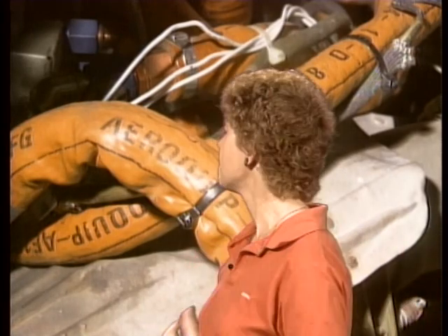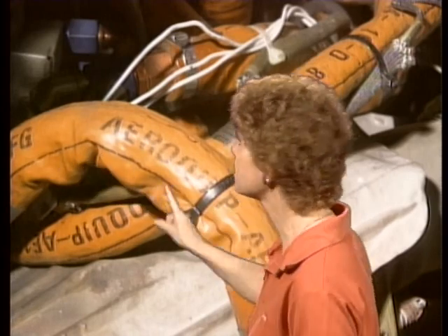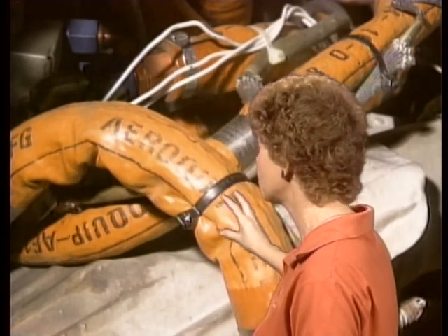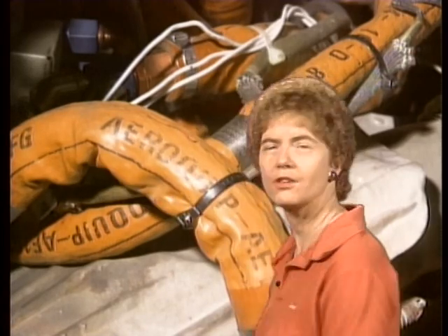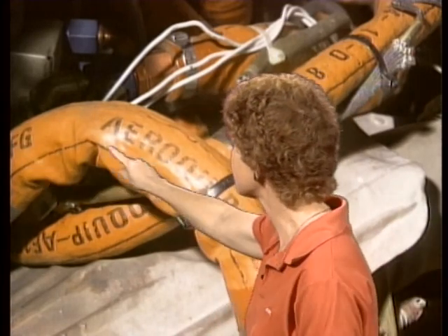Now, flexible hose has a linear stripe on it, which is also called a lay line. The purpose of it is to reflect hose twist, and hose twist is a bad thing. When you install flexible hose, it should not be twisted. A bend, some slack is fine, but it should not be twisted because that's going to reduce the strength of the hose, and the purpose of having that linear stripe on there is to tell you very clearly whether you have indeed accidentally twisted the hose as you're installing it.